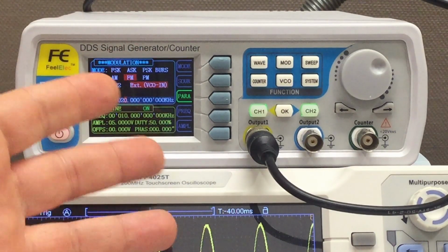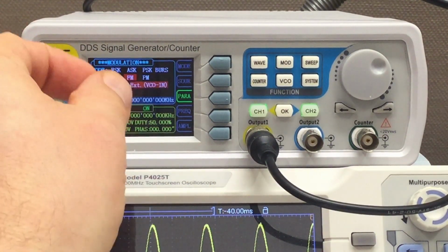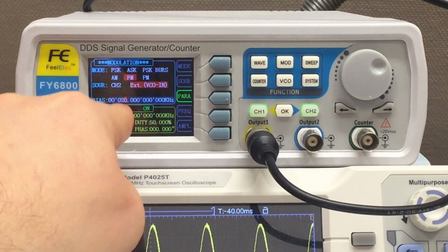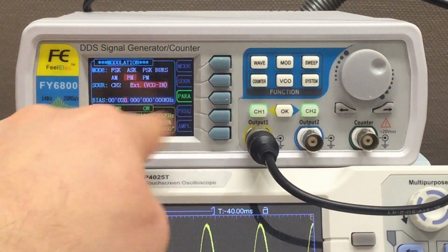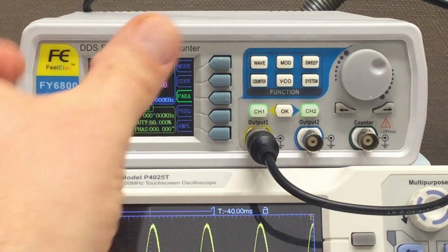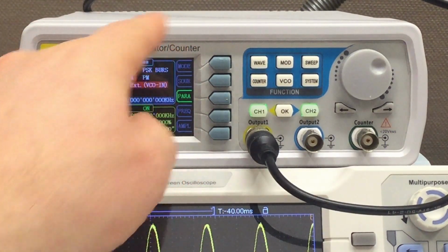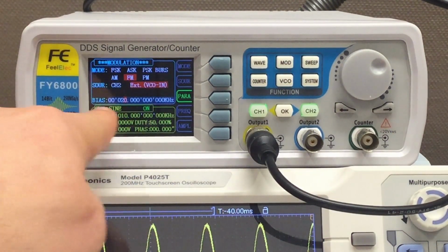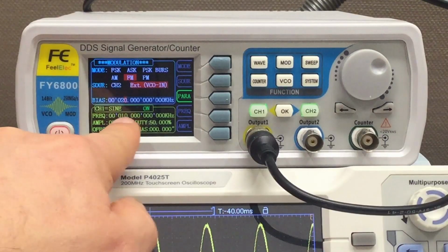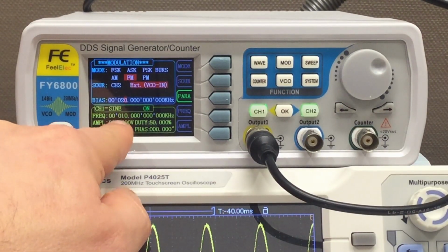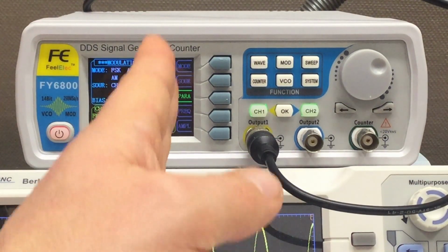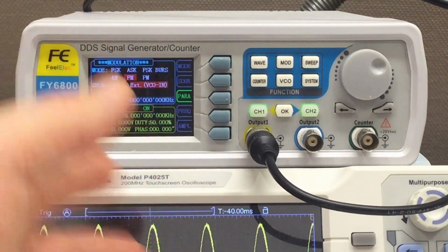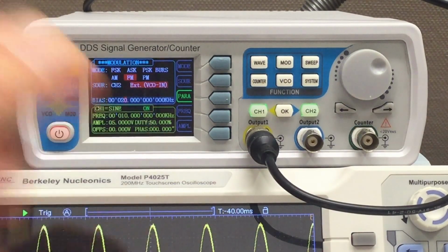So in theory, the output frequency should modulate plus minus 10 kilohertz, half of that, when we go from 0 to 5 volts at our VCO input. And there's also the channel 1 frequency here, which is 10 kilohertz, so our center frequency of our frequency modulation. And now let's do some measurements.